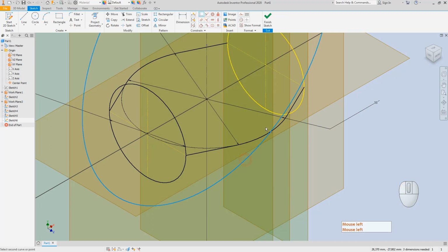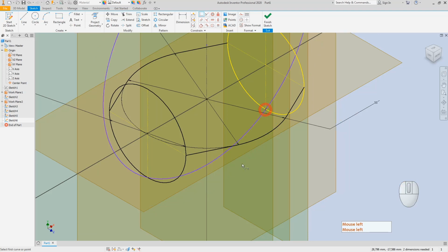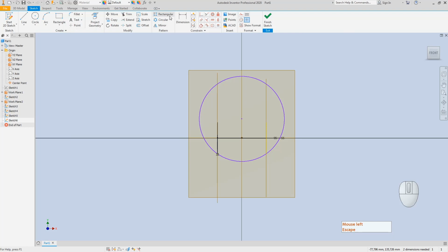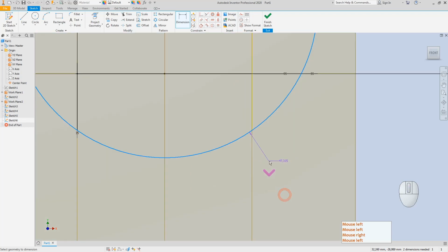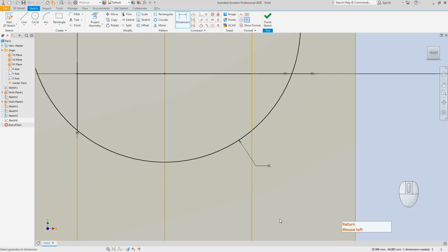We will just make coincident this circle point passing through these 2 points. We will create a dimensional relationship of this arc piece. We make the trim to get an arc shape.